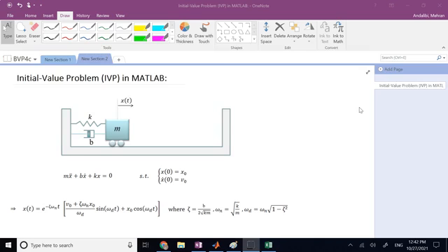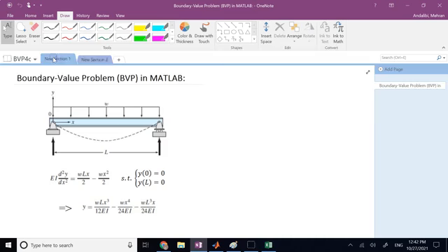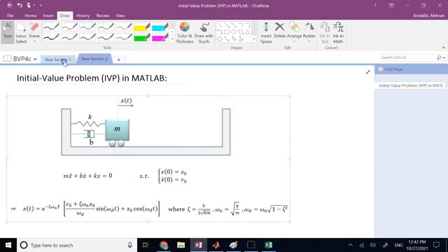The solution is going to be what we call a damped vibration if this parameter zeta, which we call the damping coefficient, is less than 1 in magnitude. And this omega n is called natural frequency, omega d is called damped natural frequency. So these are two different types of problems that we'll see a lot in engineering applications, right?